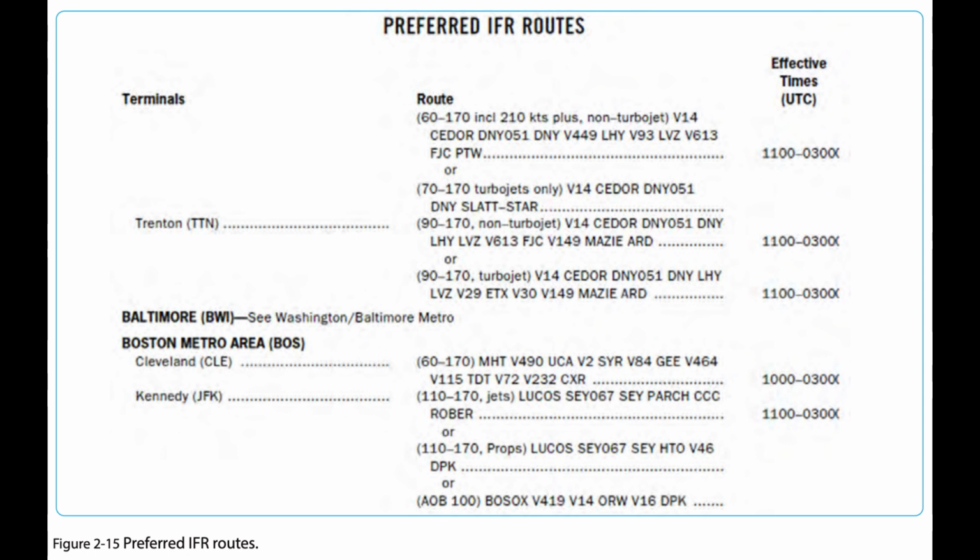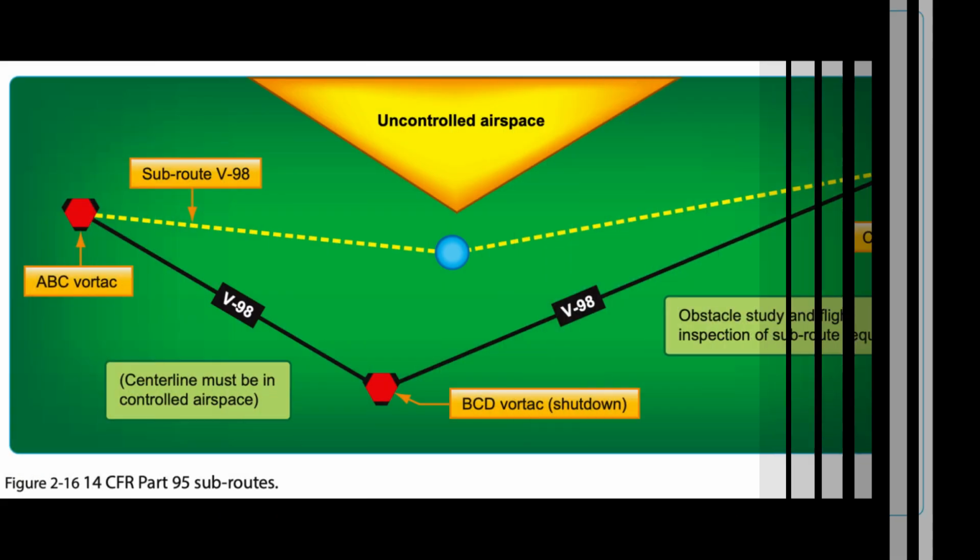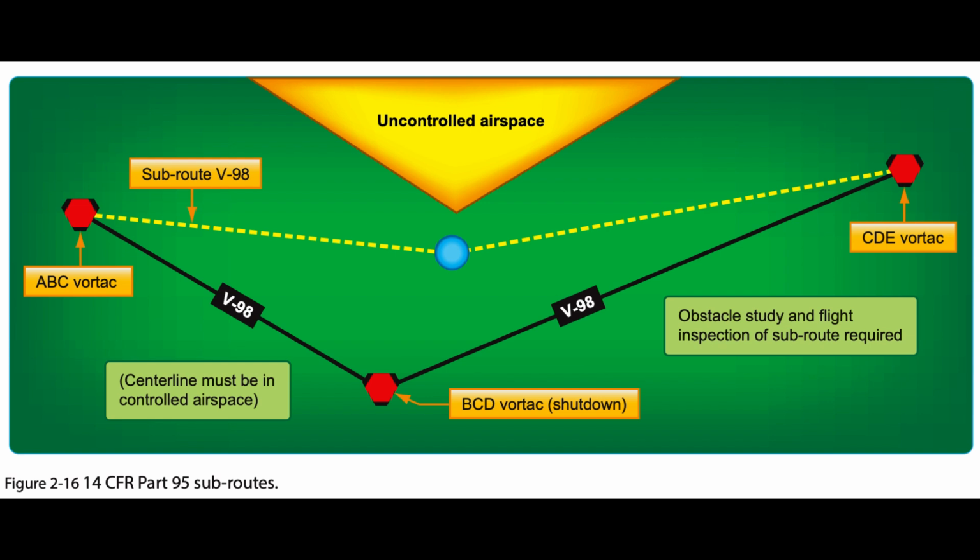Substitute airway and route flight procedures. A schedule of proposed facility shutdowns within the region is maintained and forwarded as far in advance as possible to enable the substitute routes to be published. Substitute routes are normally based on VOR/VORTAC facilities established and published for use in the appropriate altitude strata. In the case of substitute routes in the upper airspace stratum, it may be necessary to establish routes by reference to VOR/VORTAC-F facilities used in the low altitude system.